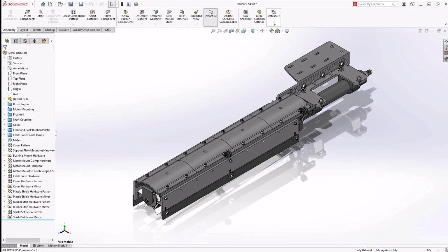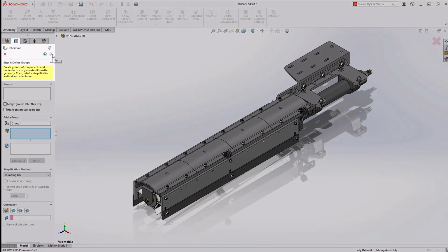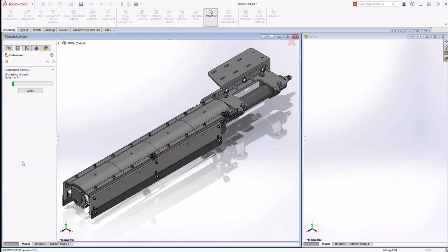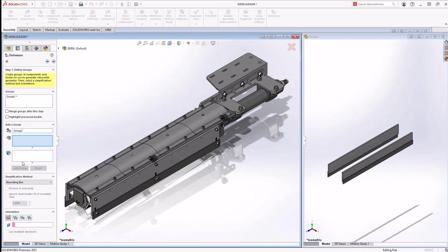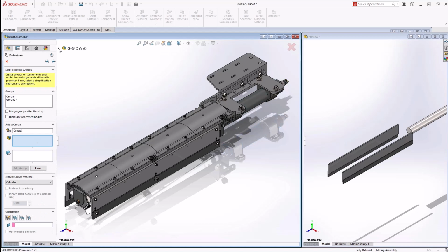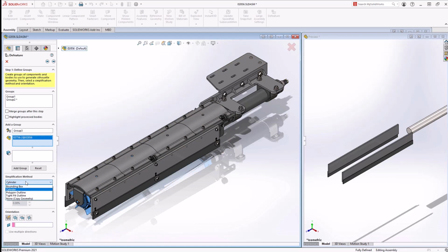Finally, we can use the Silhouette feature, introduced in SOLIDWORKS 2019, on an assembly to create a simplified representation of it or to protect proprietary information. The Silhouette feature provides an intuitive step-by-step workflow to define the simplified version using a variety of geometry simplification tools. While we are selecting the components, bodies, or subassemblies we want to simplify, we will always have a side-by-side view to show what the finished representation will look like. This ensures that we can capture the correct amount of detail.